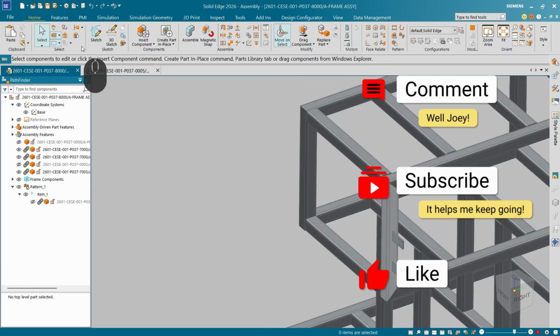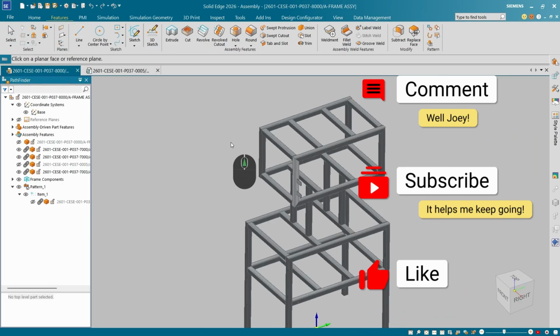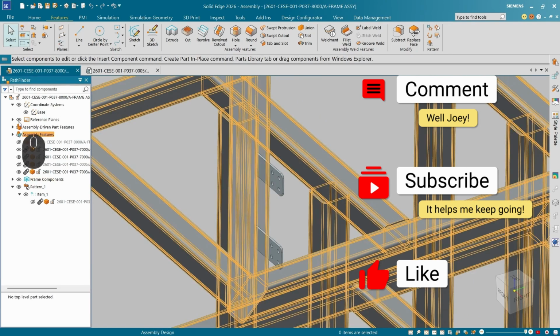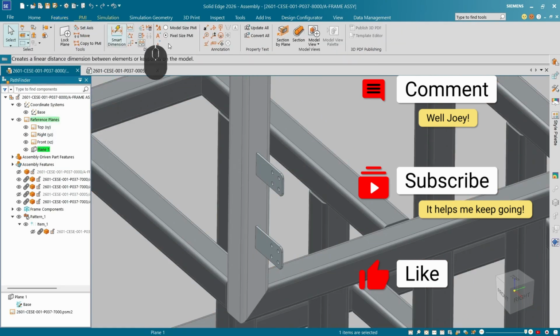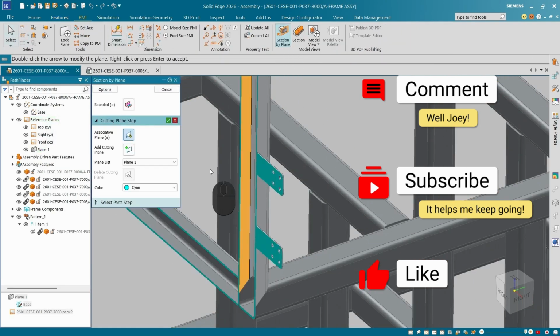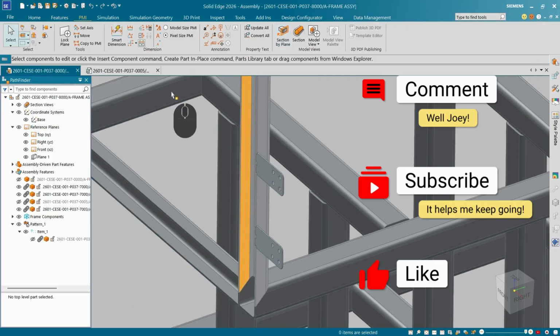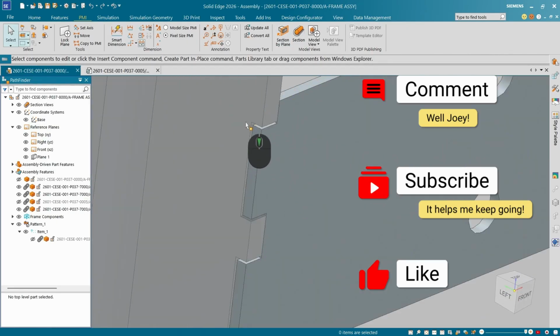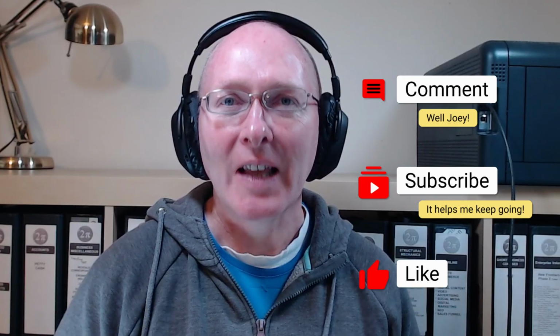I'm going to create features, parallel plane from there to the midpoint here. I'm going to select this, choose that plane, go to PMI, section by plane. Tick this box, click finish, and now we can see there's our tab and there's our slots in our box section. That's it.